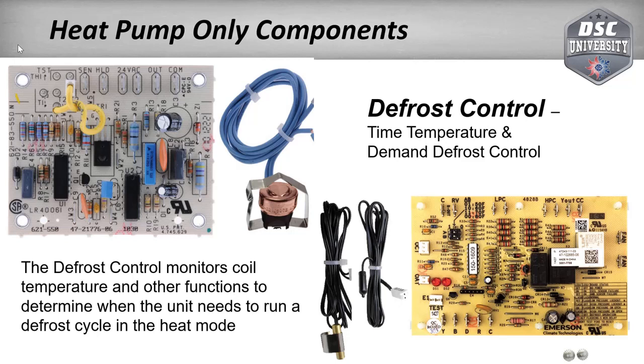It has a complex algorithm that it's using, and based on the temperature of the coil, the temperature of the air, and how long it's been running, it knows when it needs to defrost that coil. So for example, and I don't know what the exact temperature is, when the coil gets to 30 degrees, of course, at that point we should be starting to form some frost. But what if the air temperature is still 50 degrees? Then the logic will tell it that if we've been running for 10, 15 minutes, we're probably about to turn off, based on what our run time has been. And if we turn off now and it's 50 degrees outside, the coil will naturally defrost. So it prevents it from going into a defrost and wasting energy, because it can use just the outdoor temperature to do it. There's a whole lot more going on with that. That's just a simple explanation of it.